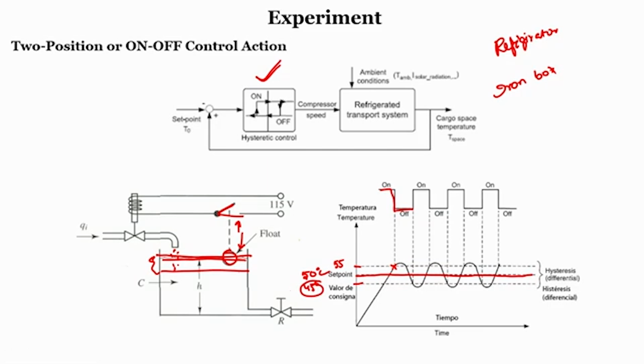If the input voltage is greater than the higher threshold point, the controller output will be off. It will switch on again only when the input voltage is lower than the lower threshold value. So, it will always fluctuate between these two thresholds. The output across the controller will be on for some time, depending upon the system parameters, then off, again on, off. Such on off operation we can see in our circuit.